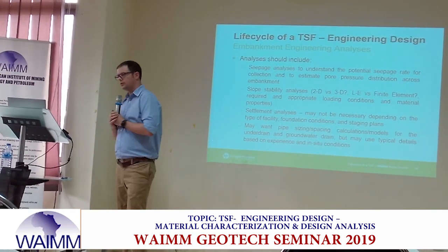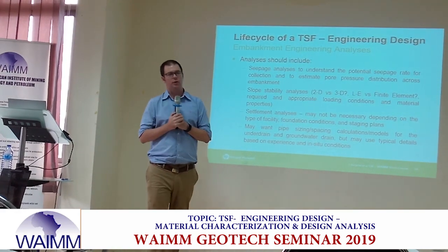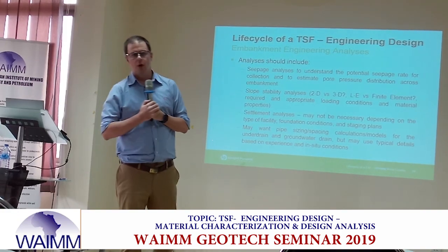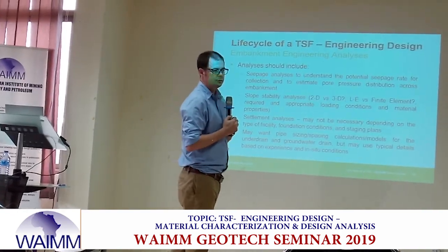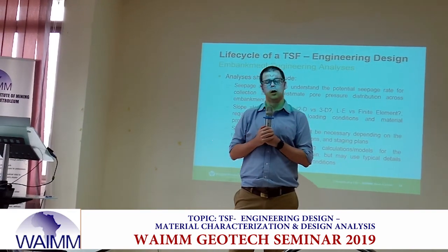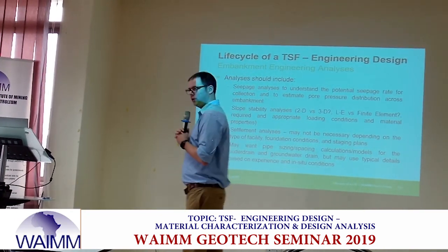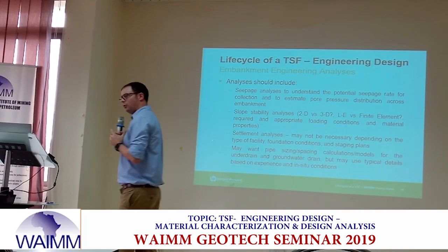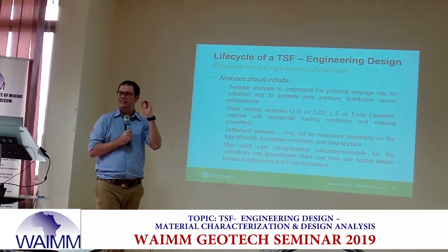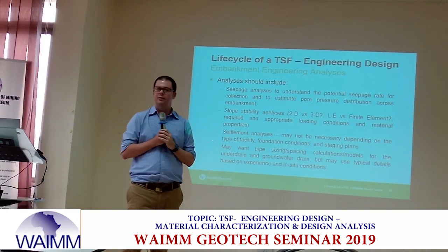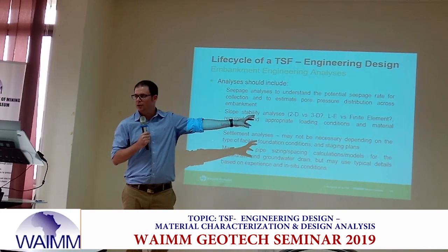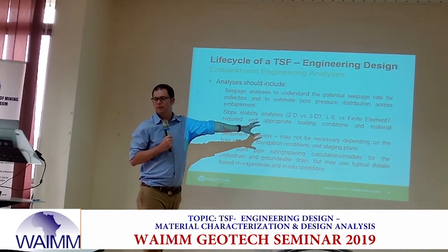someone comes to you and says, we need to dig a half-meter wide trench for our drainage system. The question I ask is, what's wrong with a half-meter wide trench? Let's say that all of the analyses say a half-meter wide trench is okay. The problem with a half-meter wide trench is, how many pieces of equipment do you own that have a half-meter wide bucket? Zero, right? So sometimes when it comes to these drainage and these pipe spacings, we go based on the size of the equipment we're going to be using.